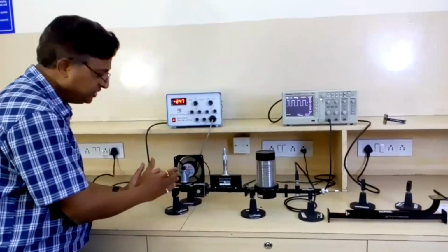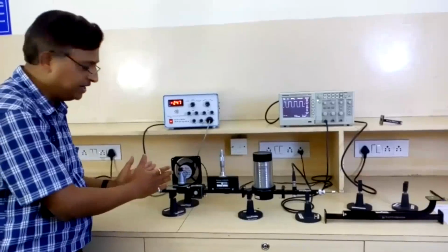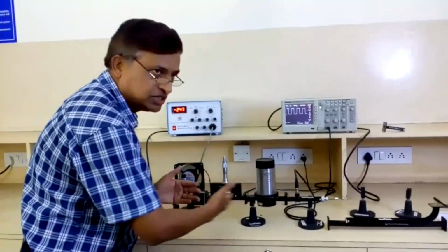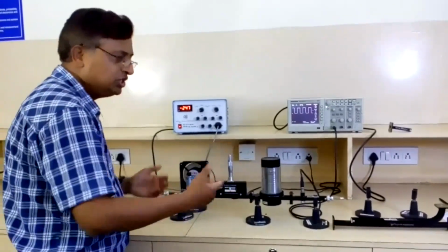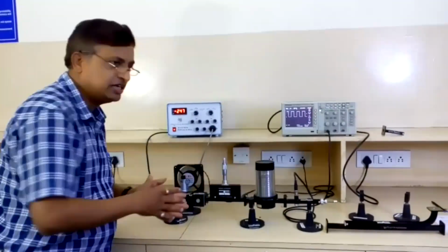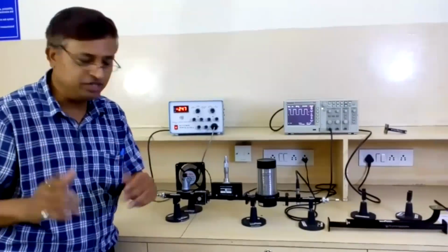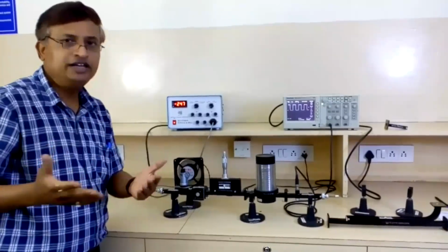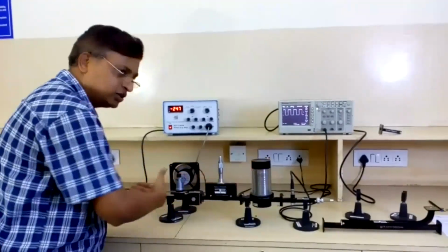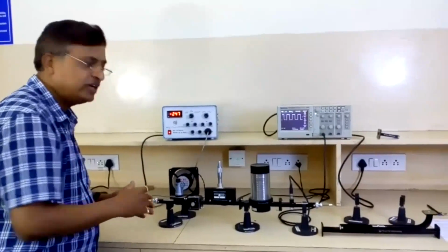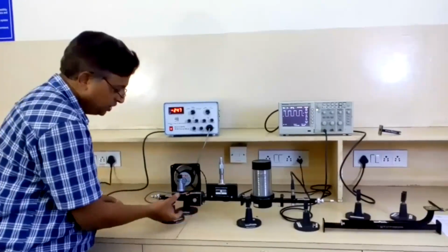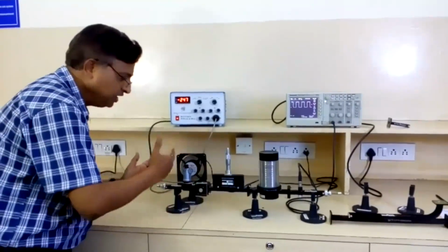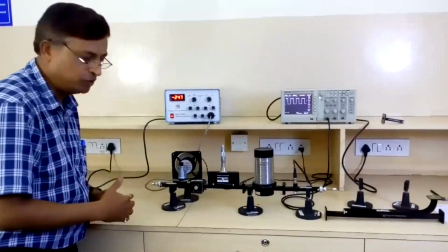Reflex klystron, as we have seen, is used as a source of X-band frequency. That source should not be damaged because of the mismatch in the impedance. In transmission line or in case of such kind of communication, impedance is one of the important parameters, where if it is mismatched, there will be reflection. To avoid the reflection and the return path of the power towards the source, we can use an isolator. So after the reflex klystron, there should be an isolator which will isolate between input and output devices and components.